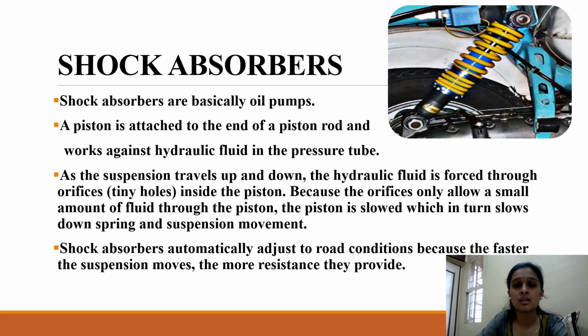As you can see in the picture on the right hand side, shock absorbers are basically oil pumps. This is completely a mechanical assembly. A piston is attached at the end of the piston rod, and they work against the hydraulic fluid in the pressure tube. So there is some hydraulic fluid that is forced to flow through the orifices, or tiny holes, inside the piston. Because the orifice allows only a very small amount of fluid to pass through, the piston is slowed, which in turn slows down the spring, which in turn reflects the movement of the suspension.